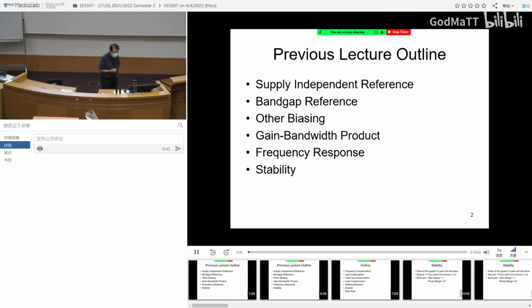And then we talked about a very important circuit block called band gap. Band gap is very popular. A lot of commercial circuits will have this band gap reference. One of the wonders of circuit is that regardless of the supply voltage, usually a range, right, from let's say 3 volt to 5 volt, or the temperature and the current, somehow the circuit will still work.